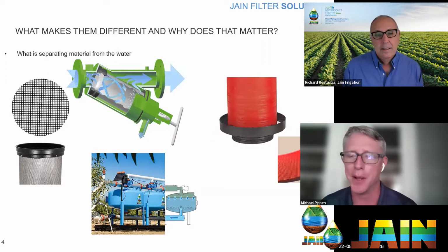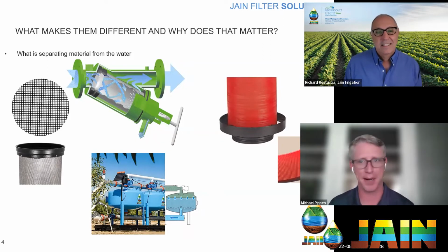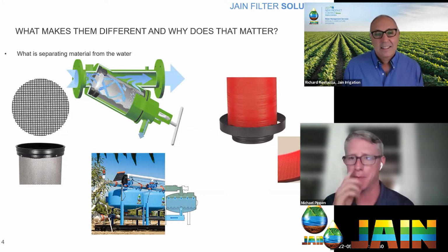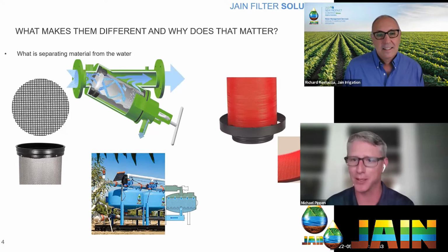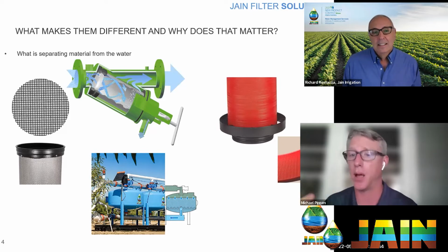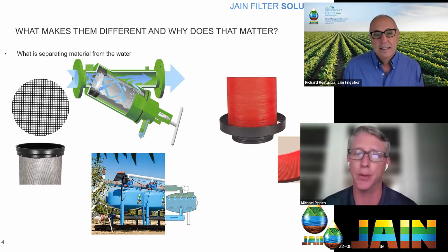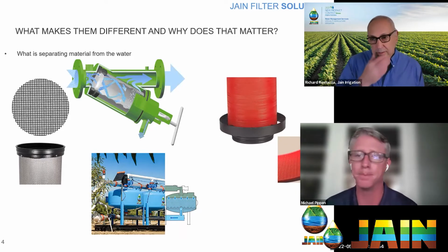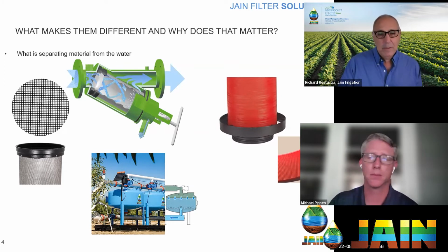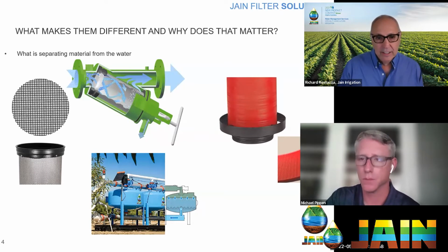There's still never a real substitute in a screen filter for just pulling it out and getting your brush that is the right coarseness and the right material to clean out that element. There really is hardly any substitute for that, but this is a really good way to keep it, if it hasn't got clogged all the way, from getting clogged up too much and keep you in operation until you have time to pull it out and get it back to completely clean. So it'll save me some labor. I won't have to clean it as often.